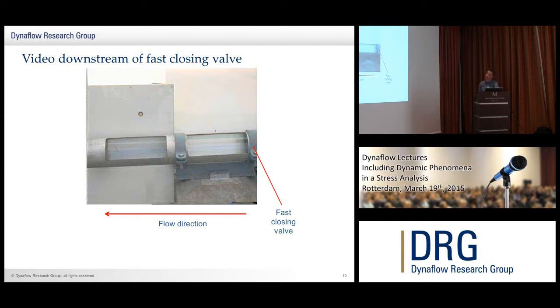And what will happen? The flow is moving from right to left, and at the beginning, it is totally full with liquid. Around this region here, because the flow is moving away, you'll end up with a void, and a low pressure region, where the liquid will reach the vapor pressure, and a gas cavity will be formed. You will see that will then implode, and I don't think we've got sound in here, so we'll have to just see what happens. Right, what you'll see now is it's actually on.